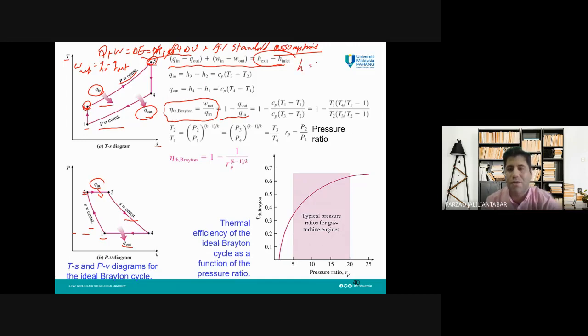Actually, enthalpy is equal to PV plus U. So in the process here, our P is constant, but volume is changed. So we need both of these two types of energy. So here we need to use H3 for a constant pressure process.